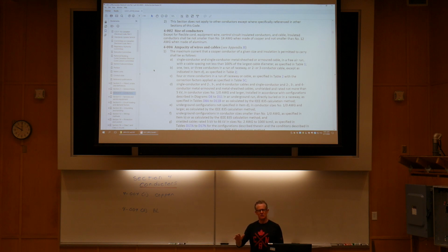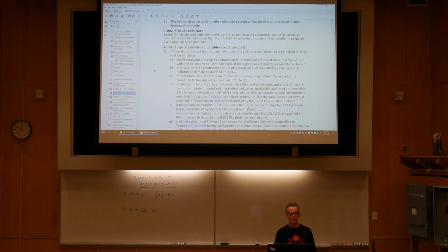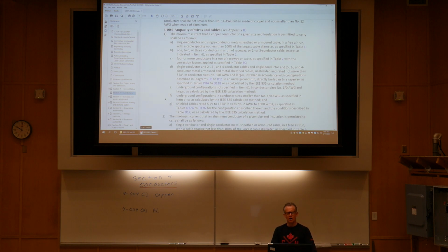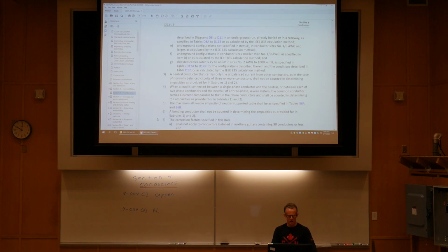All right? So when you're out in the field, a lot of the wiring that you use for service conductors, etc., is aluminum. But in your training, when we talk the Canadian Electrical Code, we're talking about copper. All right? Unless aluminum is specifically referenced in a question, we're dealing with copper. All right. So, subrule 1, A through G, is for copper. Subrule 2, A through G, is for aluminum, and they're identical.